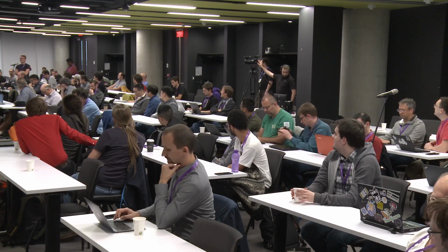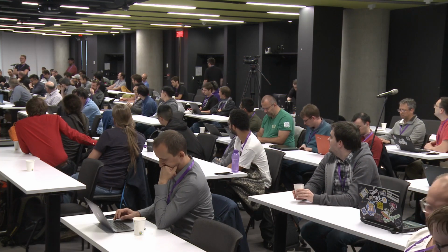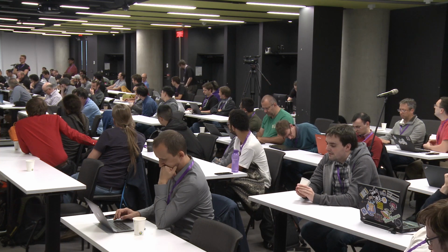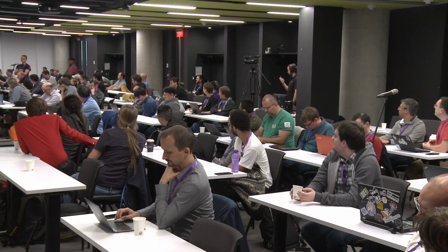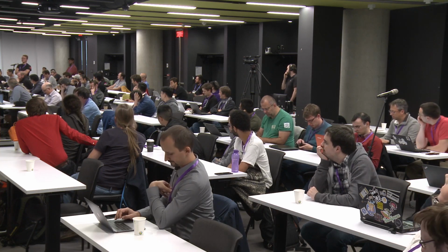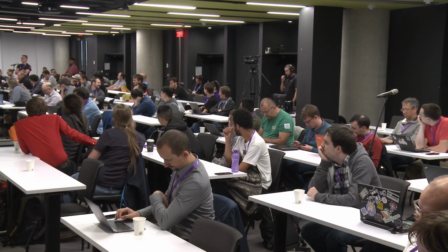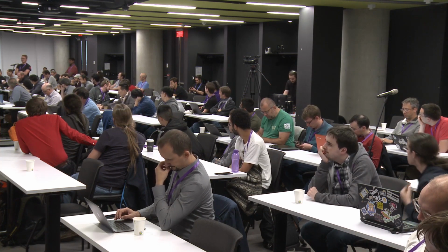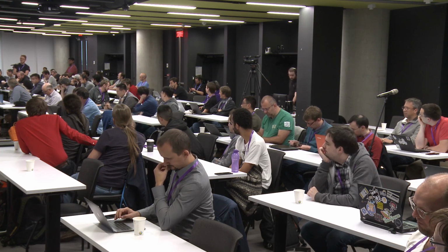No question really here. Just saying this looks like a good and interesting implementation. We've done similar stuff in AMD hardware, and I kind of like your solution in particular for that 8K, like you mentioned, even if you present one CRTC to user mode, for probably the DSC case. Yeah, for the DSC case. And we were talking last year about how to potentially solve this. It's a great solution for it, I think.